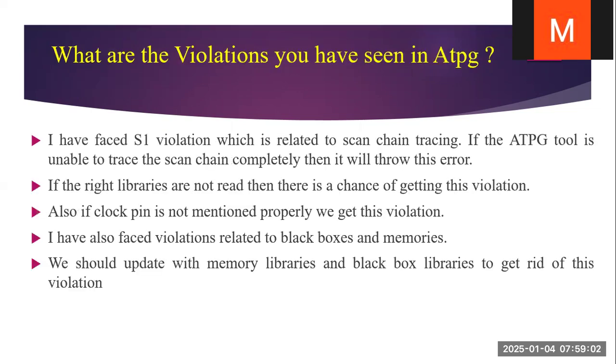What are the violations you have seen in ATPG, automatic test pattern generation? I have faced the S1 violation, which is related to scan chain tracing. If the ATPG tool is unable to trace the scan chain completely, then it will throw an error.